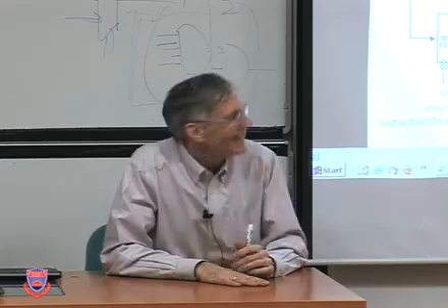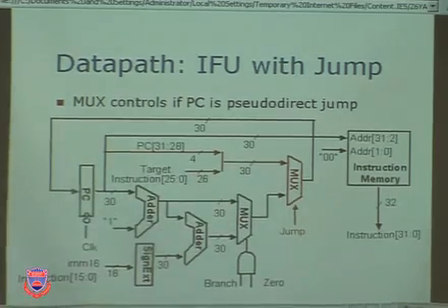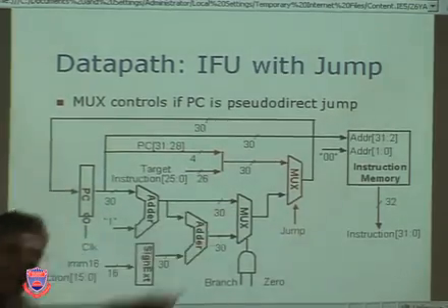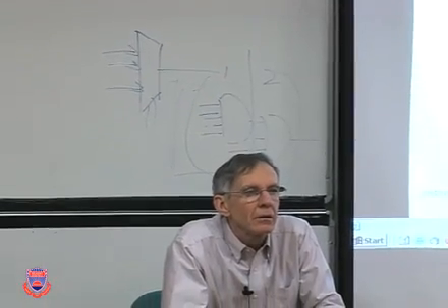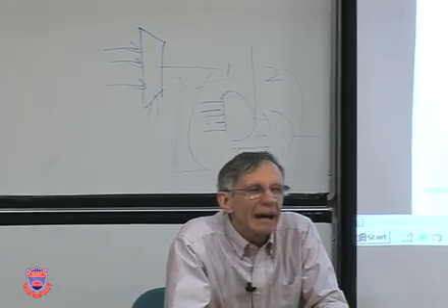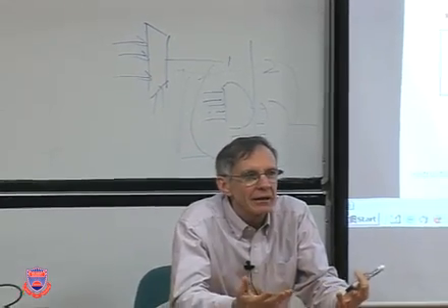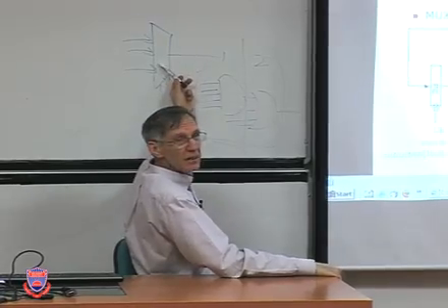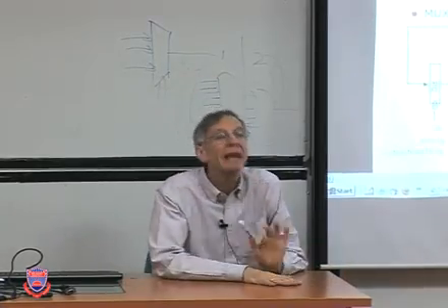He didn't say that. Okay, so the question is, this is 4-level, and this is 2-level. Is there anything to be gained by doing it that way, or lost by doing it that way? Possibly size and space. You have to look at the gate input count of this and the gate input count of this. But I tell you, I've done this before. This one's the winner. There's no reason in the world to do that except for pedagogy.